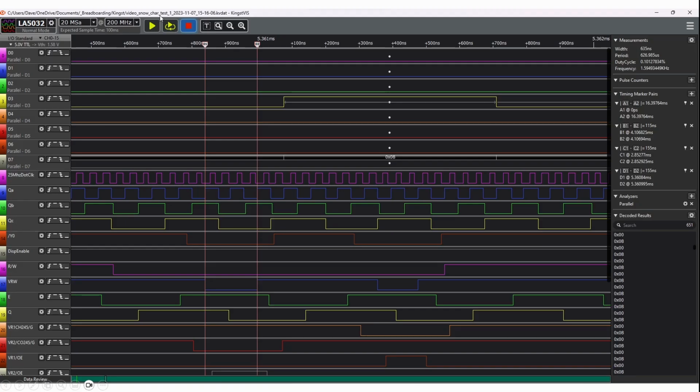So these are some screenshots of the traces that I've done, and really what I was looking for in the character mode test was the color. This basically is looking at the input to the video DAC, and we're looking for color 8, which is red on black background. When I was looking at this, I was primarily looking at the video read-write signal, which is this one down here. But as I came to understand it more, the Y0 signal here, which is when we're directly accessing the video RAM, was probably just as important, and in fact had more correlation when we were getting the interference.